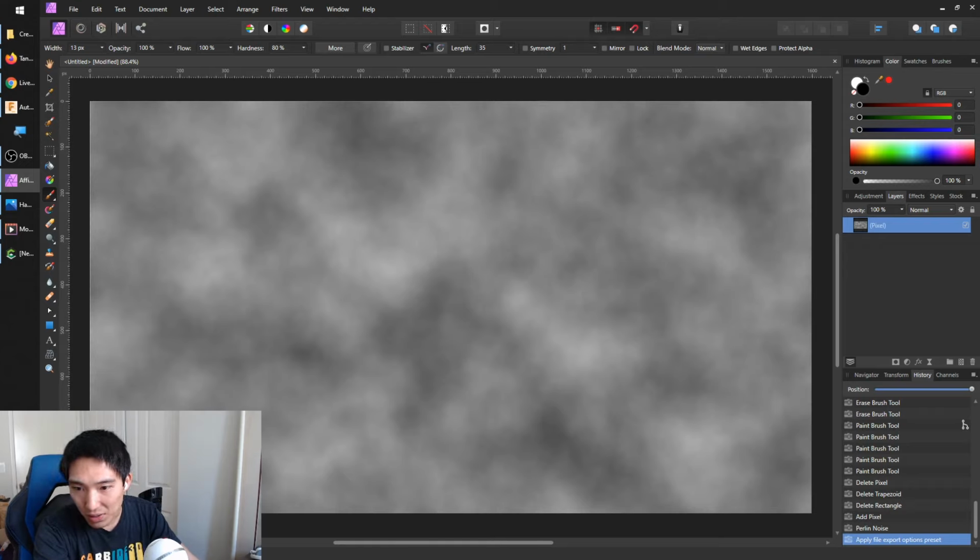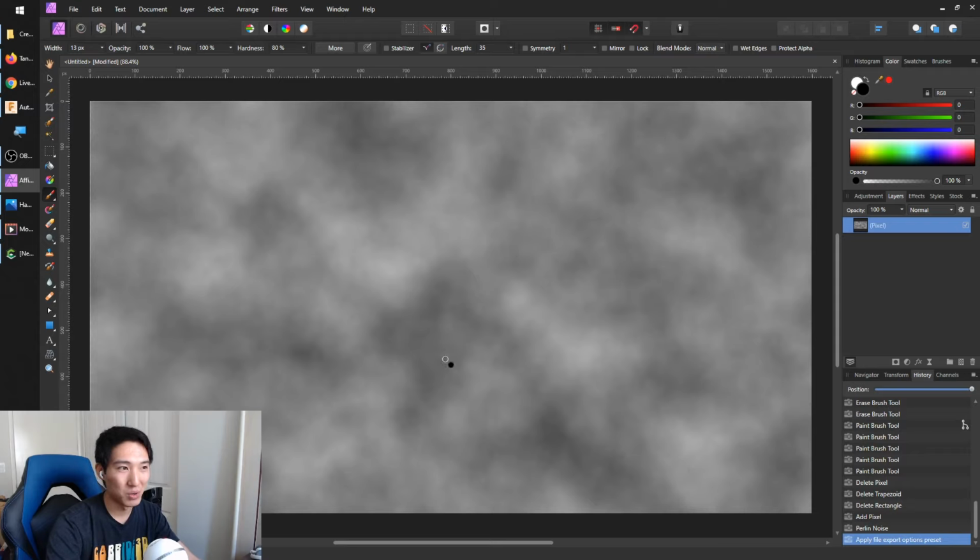Let's see, anything else? So if you could get a 3D map of something, like if you had a Microsoft Kinect, or you could map a surface, you could totally scan in an object, bring it in. There are tools that you can use to take an STL or a mesh file and then turn it into a height map. But if you had that mesh file to begin with in a native STL format, you could also use something like MeshCAM. You could turn it into an image and then do a workflow through Carbide Create Pro, or you can just work natively with that mesh.